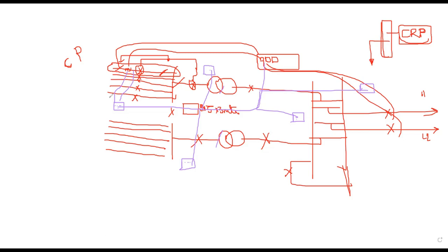Now we are talking about what the control and relay panel is. We know how they are accommodated. Now let's talk about what cables are coming in, and how the control and relay panel looks. Before that, we need relays for 33 kV. Obviously, at every breaker unit we require overcurrent and earth fault relays. Before these relays there are different types of architectures, meaning different ways of doing this scheme.